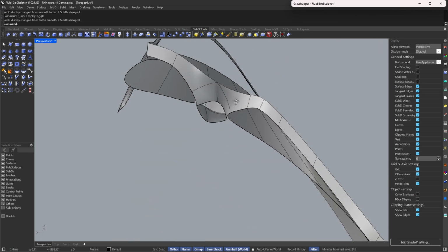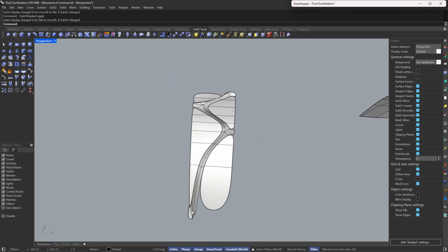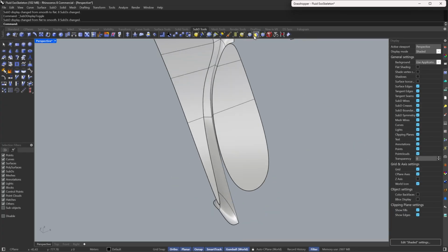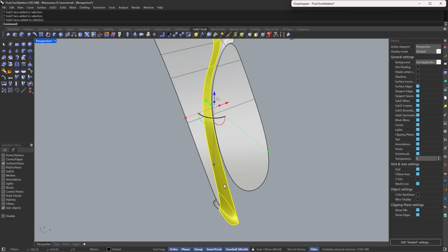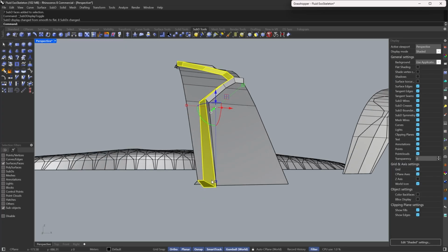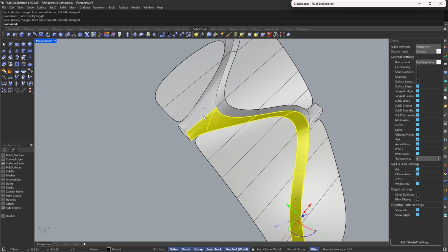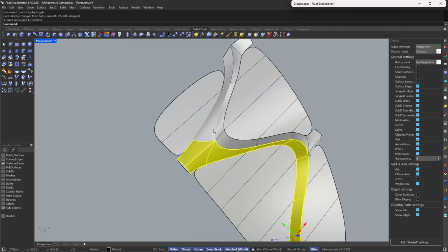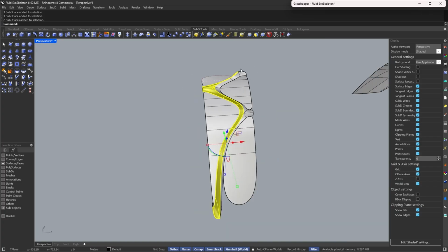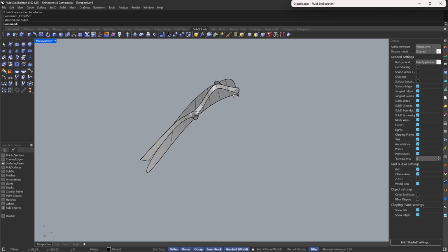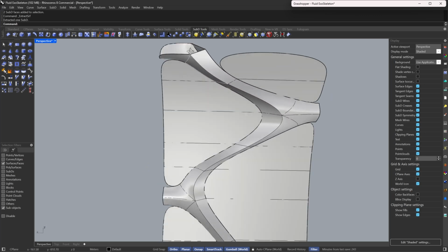And this is good. After that, the most important part is to separate them based on the creases. If this whole part is edged by a crease, then I will eliminate it. But if there is no crease in here, then I will continue until all the creases are selected, and then I'm going to extract this, and do the same for the other side.